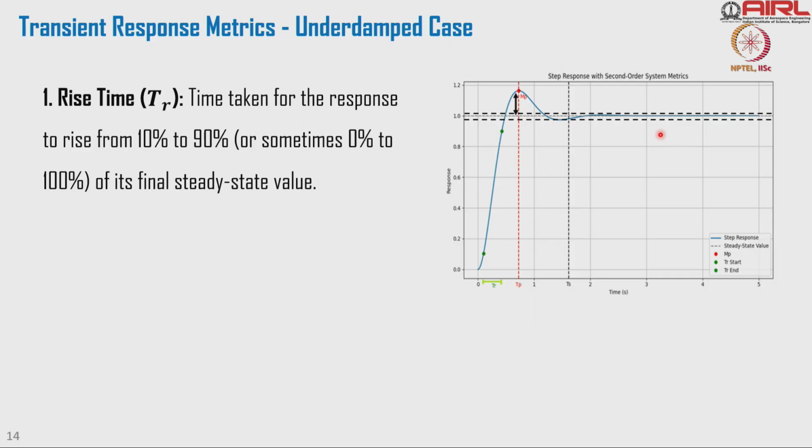We don't talk about the rise time, the settling time, the peak time, how fast the response should be, or how smooth the response should be. No, we just give the requirement in a qualitative sense. I don't want the lift to accelerate too fast. It should be comfortable. You tell me what that comfortable really translates to in acceleration, and how fast it should rise to the steady state value. So that's a bigger problem.